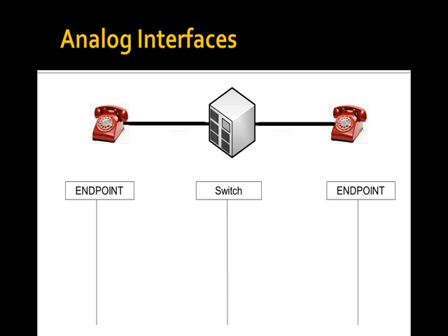The phone is no longer on hook because it's got ringing voltage going to it, but it's not off hook because you haven't picked it up. So, in other words, we've got a third state. That's that ringing one. Typically, a switch will not deliver another ringing state to it. You can kind of come up with some weird situations where you would, but normally, if a phone is ringing, it's not available for another incoming call. A second incoming call would get a busy. Okay.